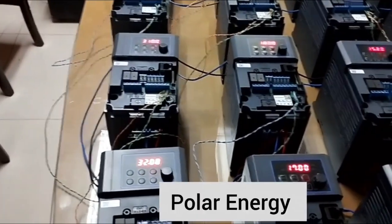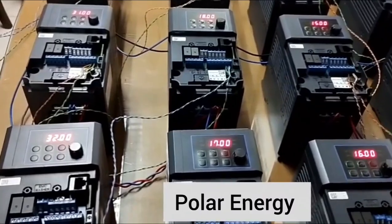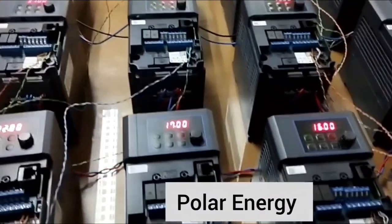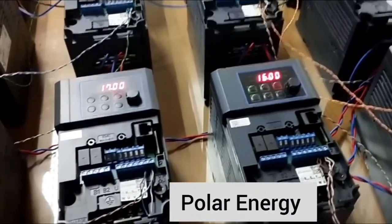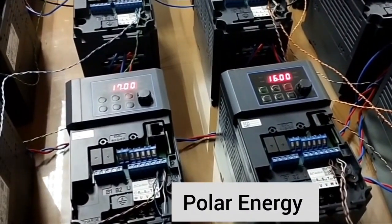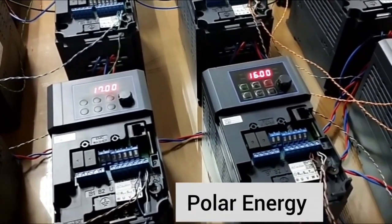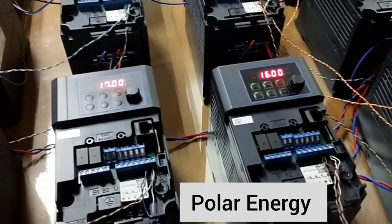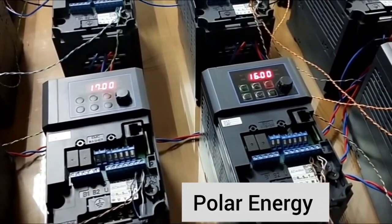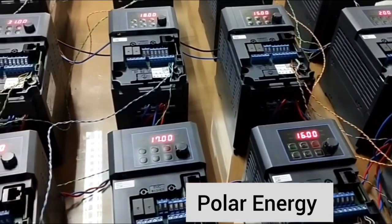The key point here is that the response time for these inverters, and I am talking specifically about the LSG 100 model, is configured to 5 milliseconds by default. Because of this, there is no need for us to manually adjust or change that response time setting. In our application, that 5 millisecond window is perfectly adequate, and it works just fine for all of our operational purposes without requiring any further modification.